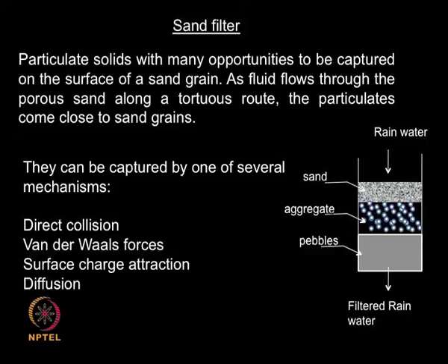They are very useful, simple, very cheap, and once you set up this type of filtration assembly, it can last for many years. As long as the percentage of solids present in your slurry is minimal, these depth filters are extremely advantageous, and the operating cost is practically zero.